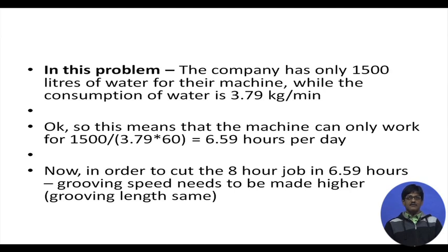Now, in order to cut the 8-hour job in 6.59 hours, grooving speed needs to be made higher. Naturally, if you are grooving, and if this grooving is taking less time, that means your speed is increasing. So, grooving speed needs to be made higher. Grooving length is the same, you are cutting the same job, and mind you, you have to produce the same grooving depth also. So, we have two conditions to satisfy.